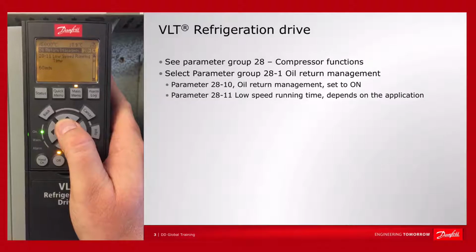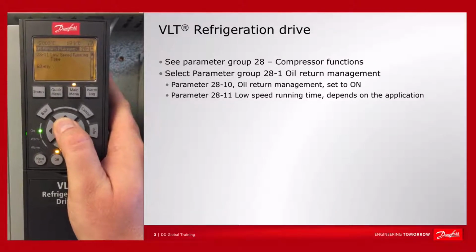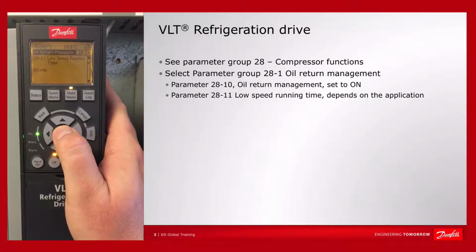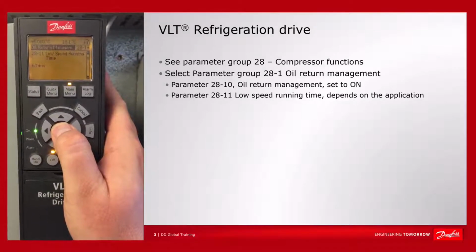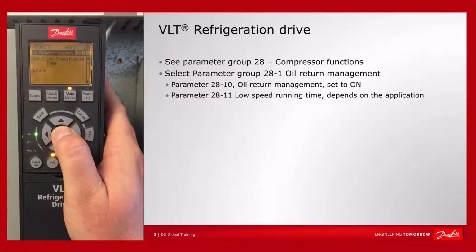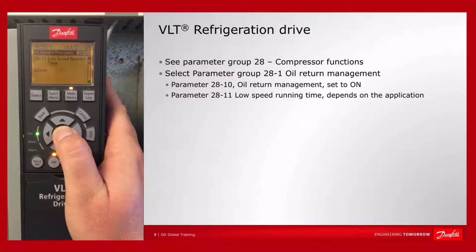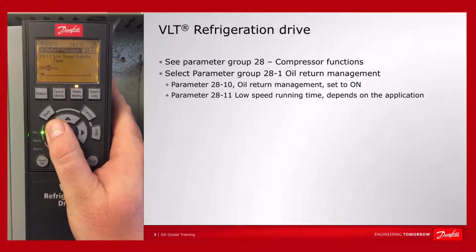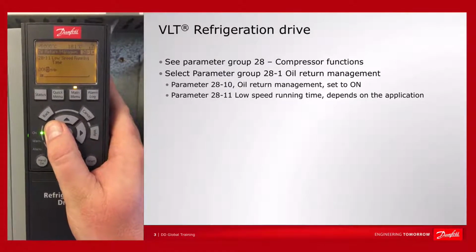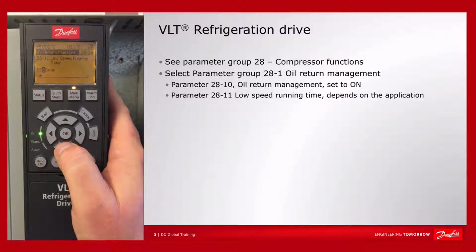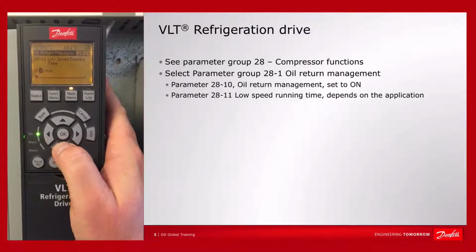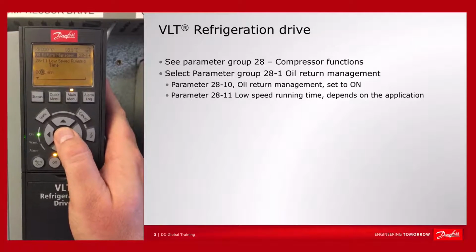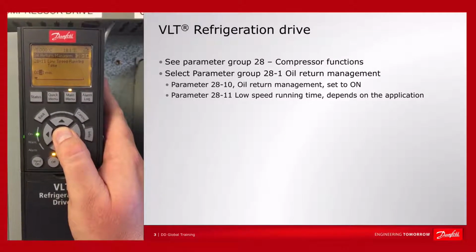and you must determine for how long the compressor should be running at this particularly low speed before it's a dangerous situation. This depends very much on the size of the compressor and the system in general, so general advice cannot be given. But it could be 30 minutes, it could be 60 minutes, in some cases maybe even 6 hours. I'll program 1 minute for this demonstration purpose. This is usually too short, but in this case it will be okay for demonstration purposes.